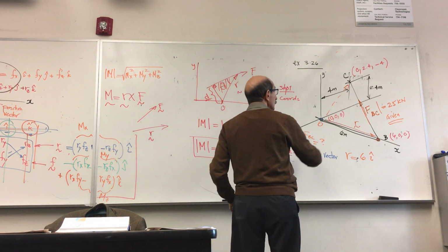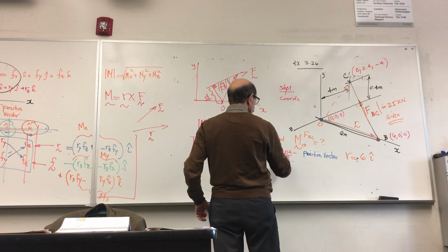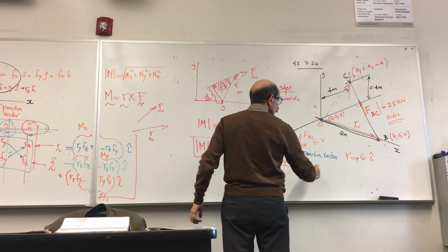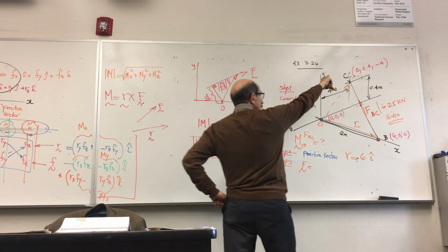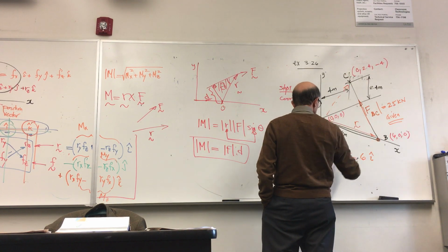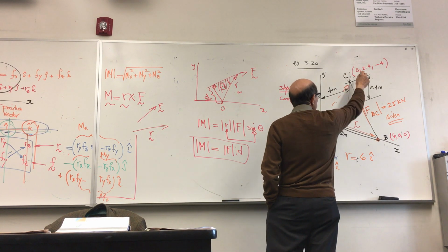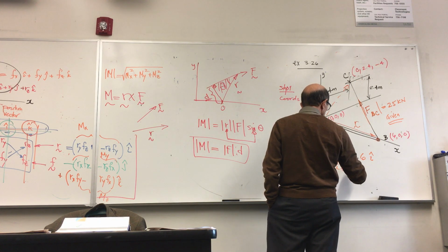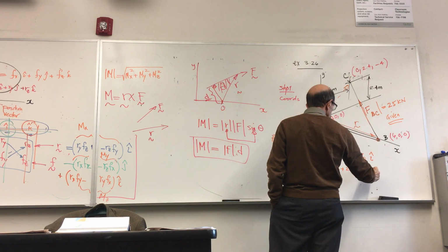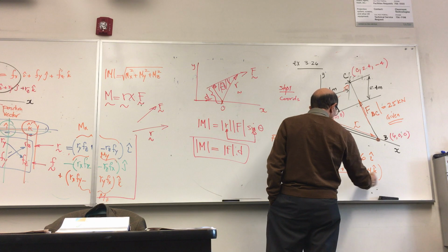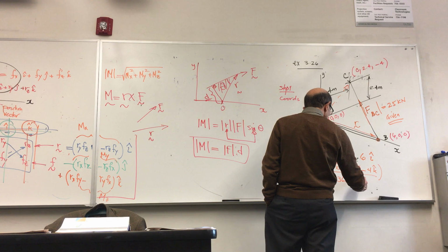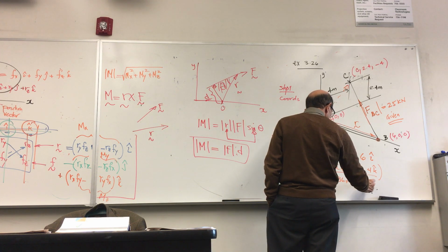Okay, so now step 3 would be to write the vector equation for the force. So you need to write again the unit vector times the magnitude. So 25 times the vector, 0 minus 6, minus 6i, 2.4 minus 0, plus 2.4j, and minus 4 minus 0, minus 4k, divided by the square root of 36 plus 5.76 plus 16.